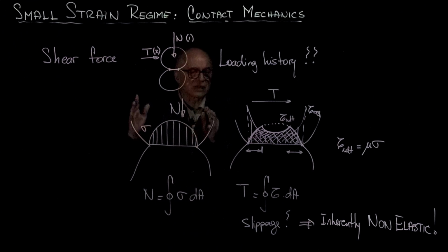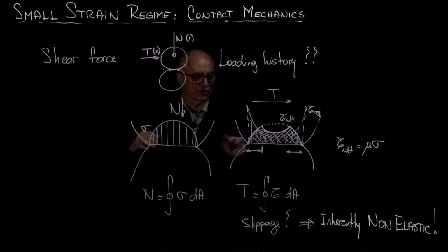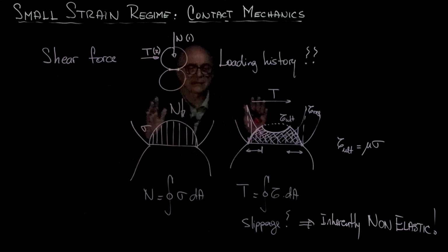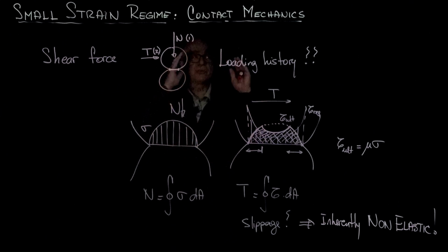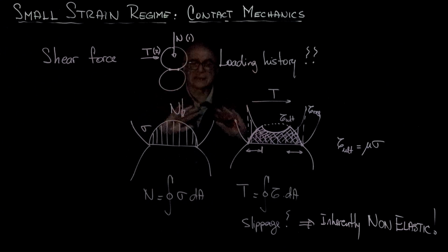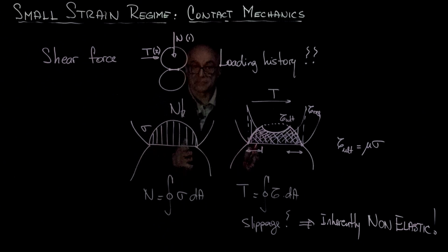If we impose a minimum of 1 angstrom deformation, there will be a threshold level for true elastic behavior, even in granular materials. But I think that the real take-home message is that from a point of view of contact mechanics, we can categorically conclude that soils are inherently nonlinear, non-elastic, because soils are granular materials.